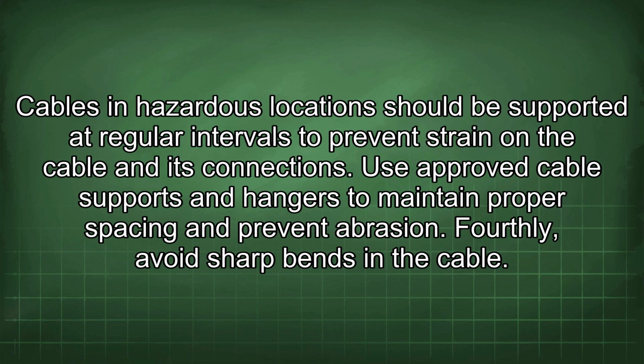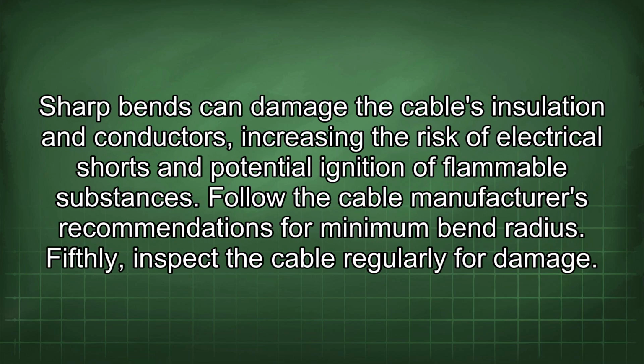Fourthly, avoid sharp bends in the cable. Sharp bends can damage the cable's insulation and conductors, increasing the risk of electrical shorts and potential ignition of flammable substances. Follow the cable manufacturer's recommendations for minimum bend radius.